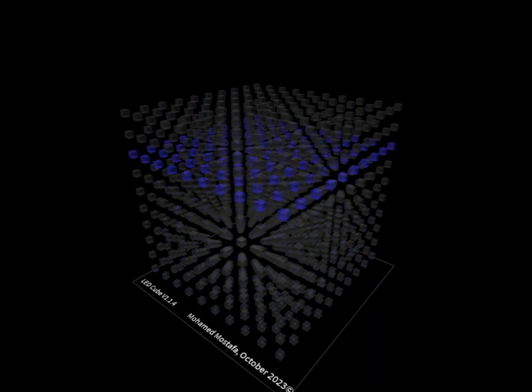For a small LED cube, 3x3x3 or 4x4x4, you might get away with connecting the cathode layers directly to a microcontroller I/O pin. For a larger cube, however, the current going through this pin will be too high.